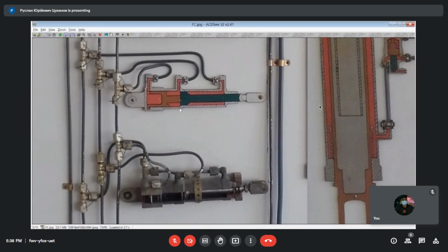It has bigger diameter. Here you see a step in diameters. And so it provides, in a rather simple manner, three positions of the high lift devices. When you need to extend flaps, you supply high pressure fluid, permanently supplied to the right connection here, and both other connections are attached to the return line.